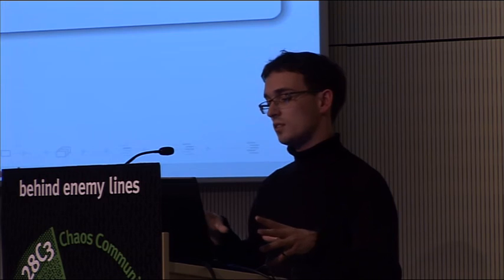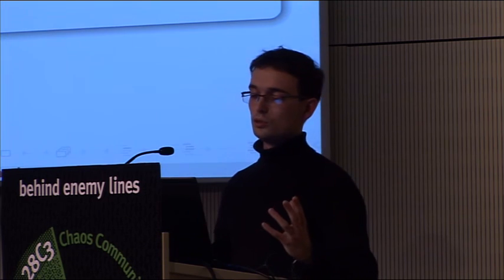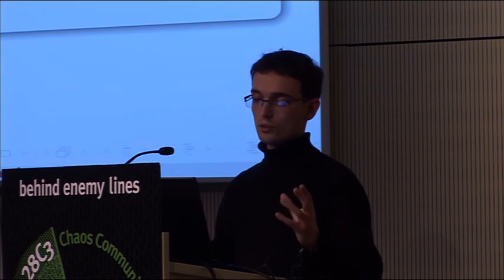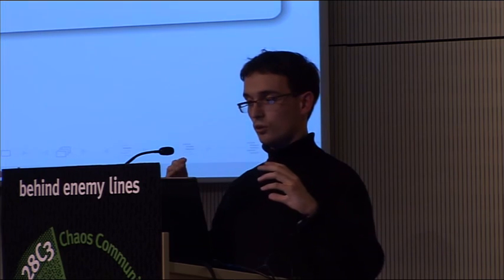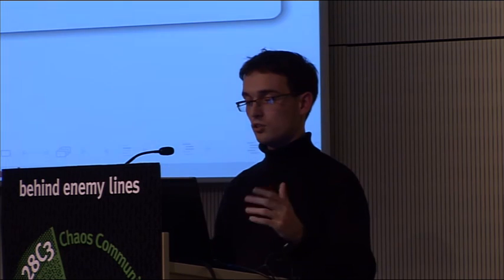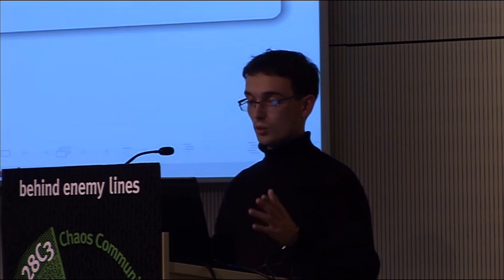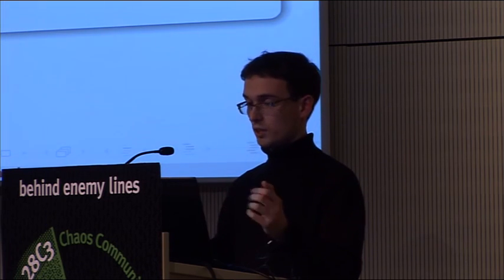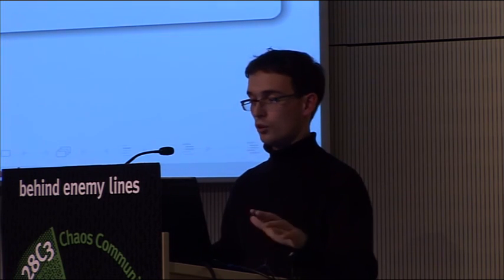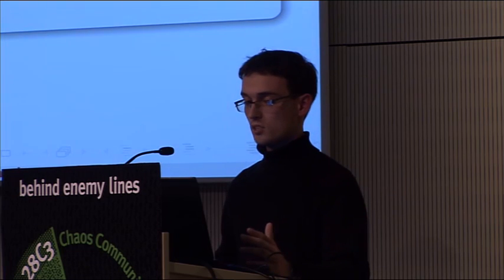There is also the DS task. The DS task is a data service task. It's used to unify all the gathering of protocol stacks at the lower layers. It will fetch all the data and put it into pipes so that you can see the data as a continuous stream of data, like a network flow. So it's very widely used all across the baseband, all across the system.